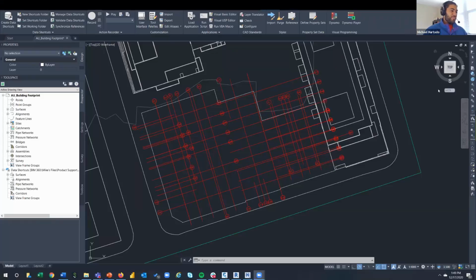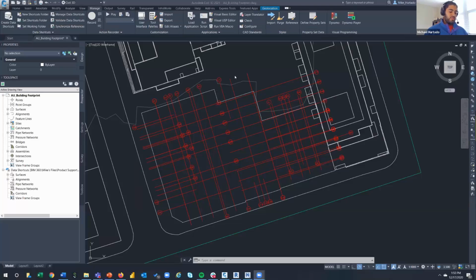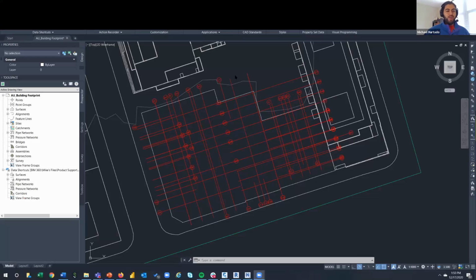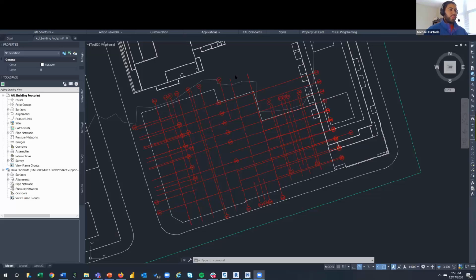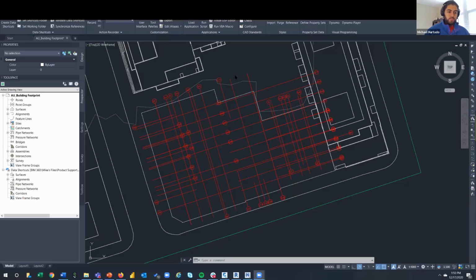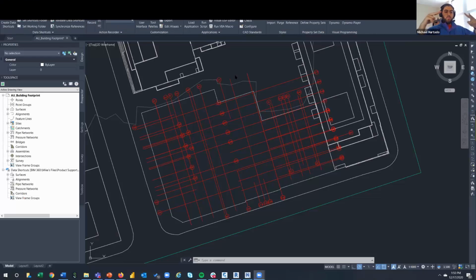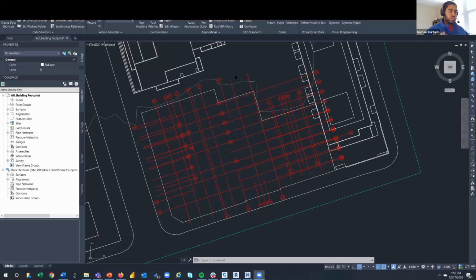I taught this class at AU 2 years. My first year, I would not rely on a grid and my elevations would come in wrong. So yeah, I have a grid now. And the best way to think about this is you need to be able to select 2 points in civil that you can then select in Revit. And those 2 points is how the two softwares are going to interact and talk to each other and handle this exchange.